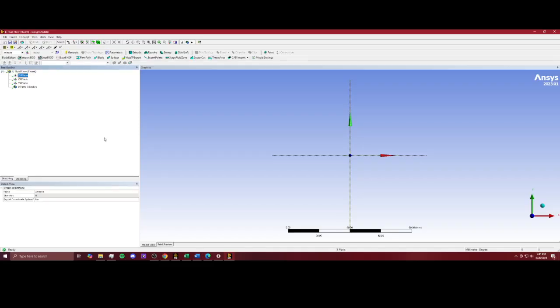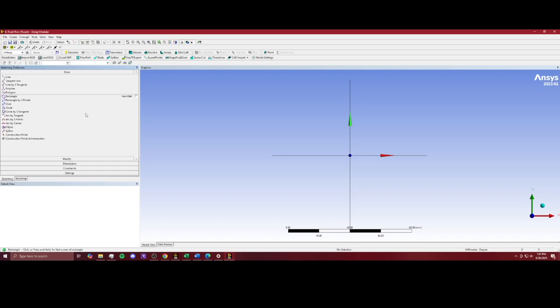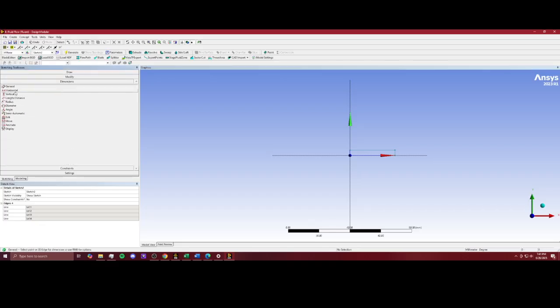So we're gonna go over here, click XY plane, make sure it's straight. So the Z-axis is what you're looking at. And then we're gonna go over here, click sketching, the rectangle, and then we just click and drag. And then to get it where we want, we're gonna go to the dimensions we want. We're gonna go to dimensions tab right here. Click on horizontal, connect these two vertices in the edge.